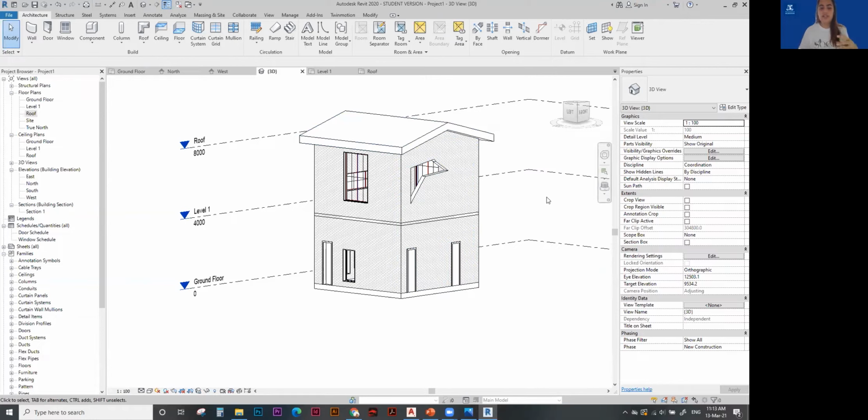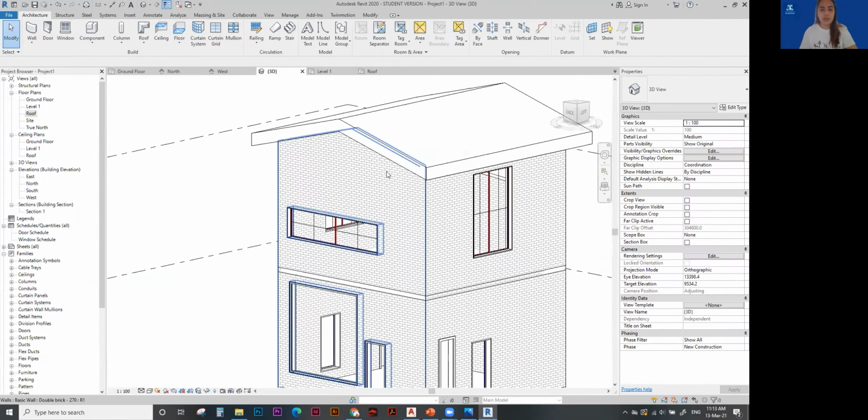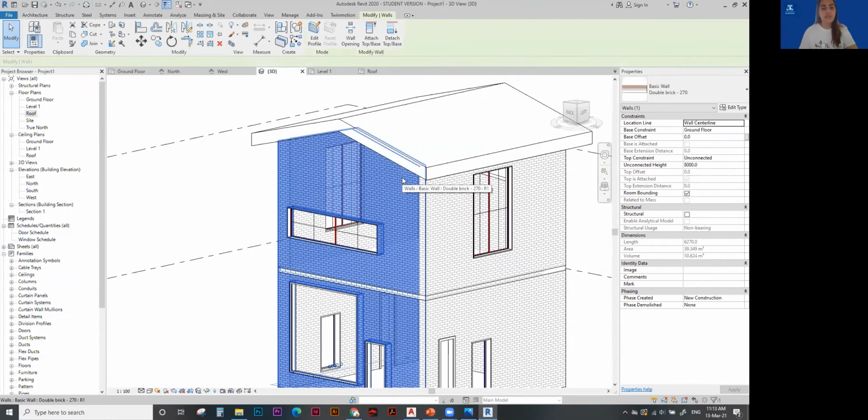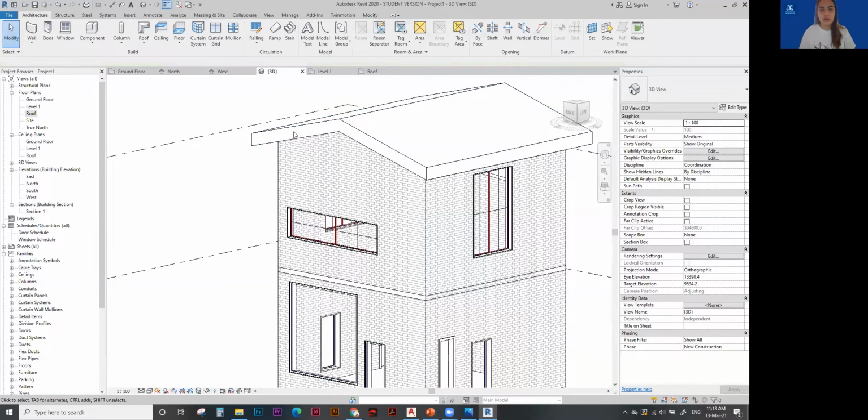And originally our wall was only till this level over here. When it asks you, do you want to attach the walls to the roof? It basically takes the walls, which are away from that side of the roof, to go and change their basic boundary to attach with the roof. That can be done otherwise as well. If you say you didn't select that while making the roof, let me show you how you do that.